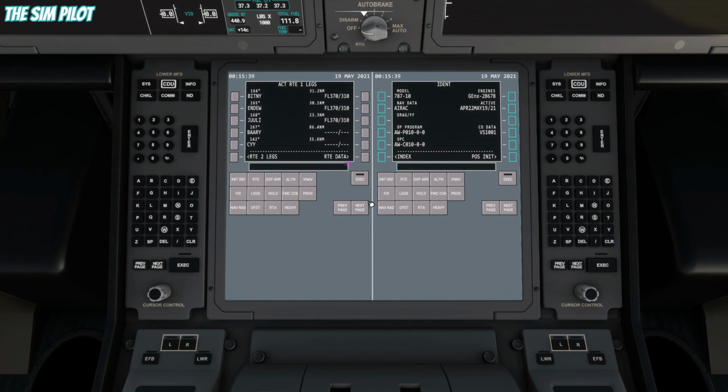You can set some restrictions if you like to certain waypoints, like if I'm at flight level 370, so let's say the ATC tells me to cross this waypoint at 20,000 feet, I can put a restriction of flight level 200, place it in here, it will cross that waypoint, and VNAV will calculate this when calculating the VNAV descent path, which is great. So that's the legs page.